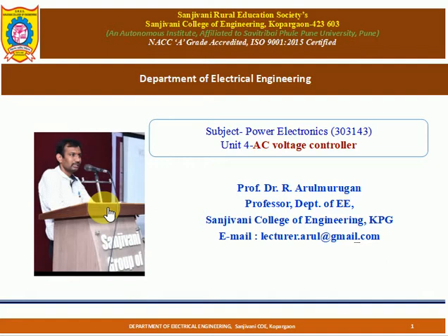In electrical machines, AC electrical machines, you use the auto transformer. What is the purpose of the auto transformer? Fixed AC into variable AC. You want to achieve variable AC. How do you achieve it? There is a variable knob. You vary it from 0 to 230 volts or 0 to 440 volts, and when you vary it, you get a variable AC output voltage.